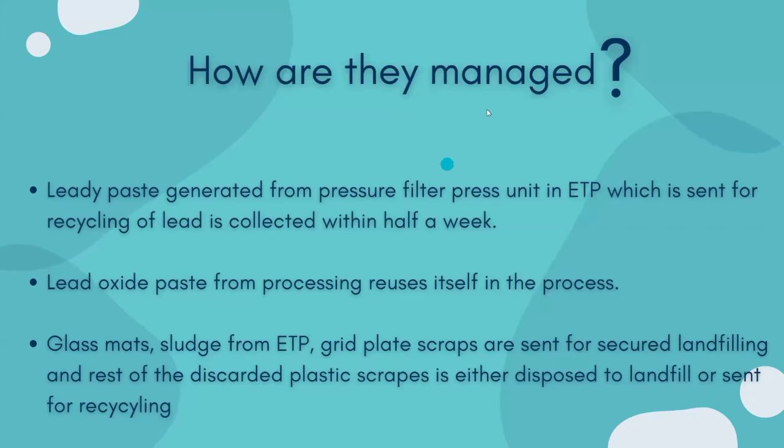Yes. So the big question is, how are they managed? The leady paste generated from the pressure filter press unit in ETP is sent for recycling of lead. Around 200 kgs of lead is collected within half a week, but fortunately it has not directly affected any worker. Lead oxide paste from processing is reused in the process. Glass mat, sludge from ETP, and grid plate scraps are sent for secured landfilling, and the rest of the discarded plastic scraps are either disposed to a landfill site or sent to recycle.